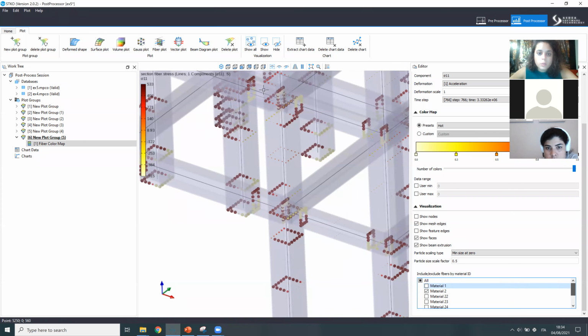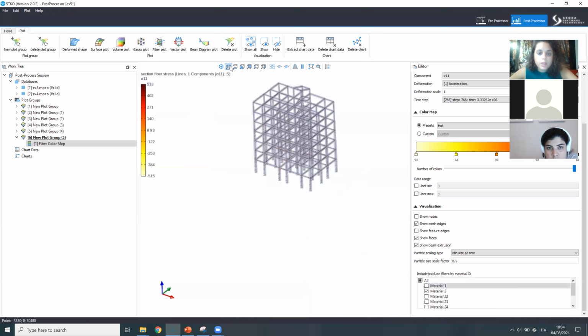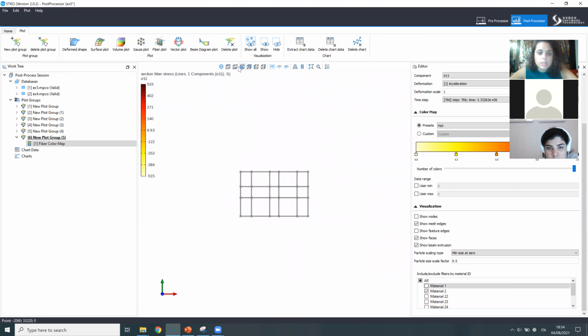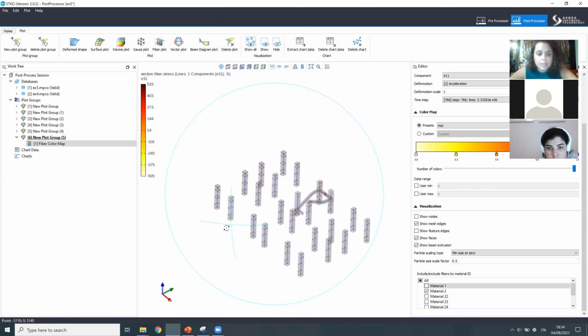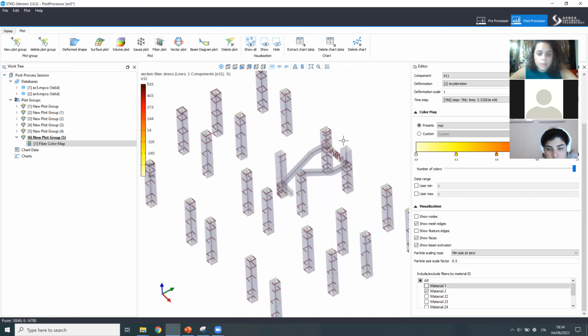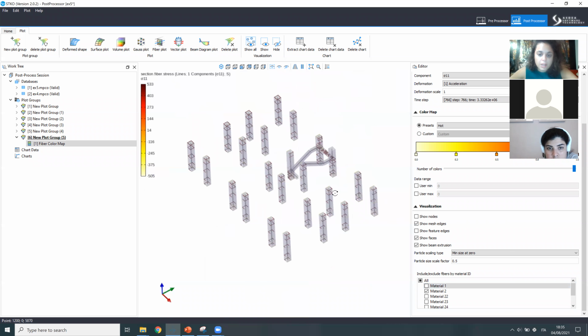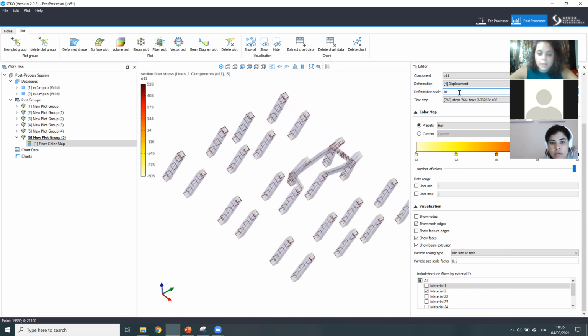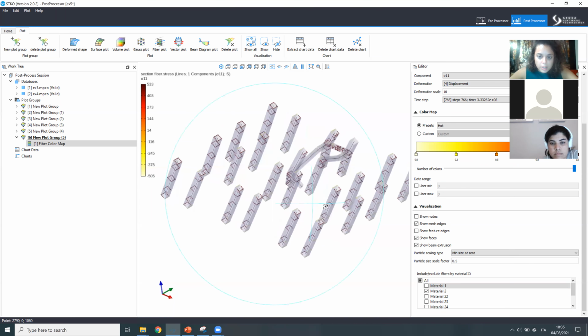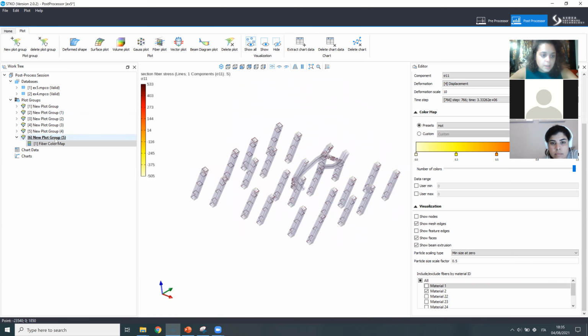What can also be interesting is, if you want to isolate only the base elements where you will have the maximum stress anyway. This way you can zoom in and not have a lot of stuff in between, and maybe plot a result in terms of displacement or deformation.